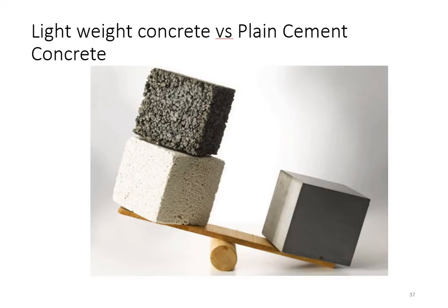Pumice stones you might have seen. You might have been using pumice stone for scrubbing your foot. If you replace the aggregates with pumice stone, then you get a lightweight concrete. You can see the weight of the lightweight concrete versus the cement concrete. This lightweight concrete is mostly used in multi-story buildings as the height increases. So, generally, we go for lightweight concrete for multi-story buildings. Towards the top stories, we go for this lightweight concrete.